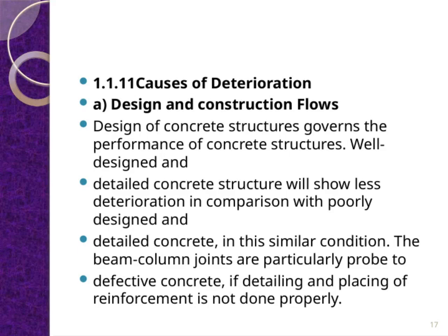Now, let's talk about the causes of deterioration, starting with design and construction flaws. The way we design concrete structures really influences how they perform over time. If a concrete structure is well designed and carefully detailed, it will generally show less deterioration compared to one that's poorly designed, even if both are in similar conditions.